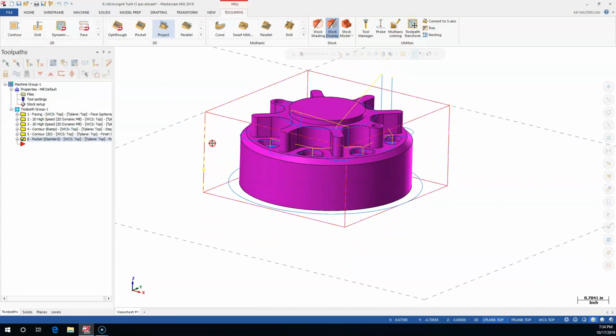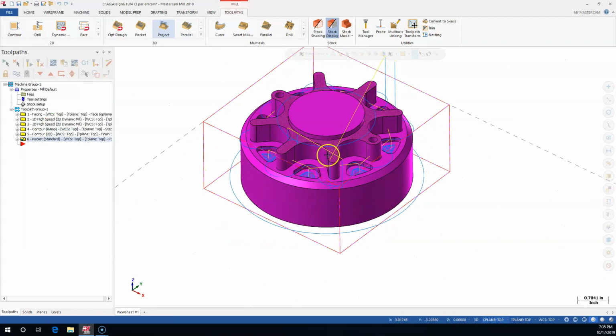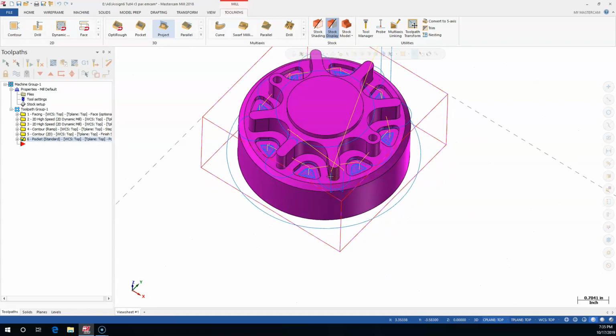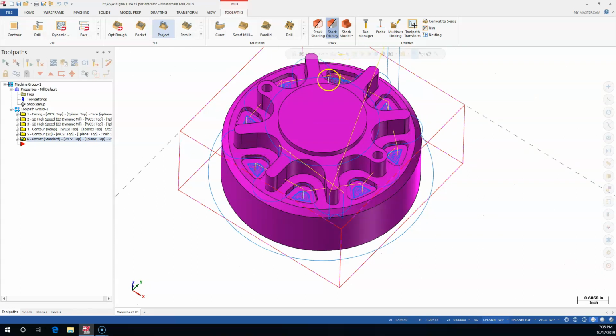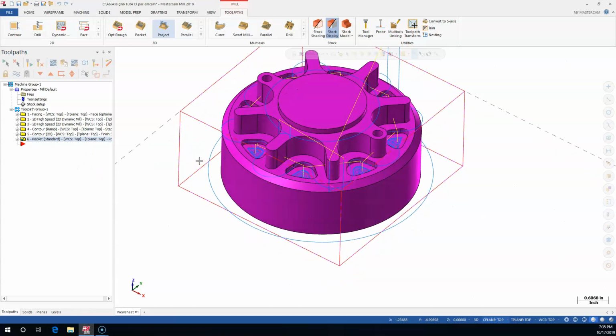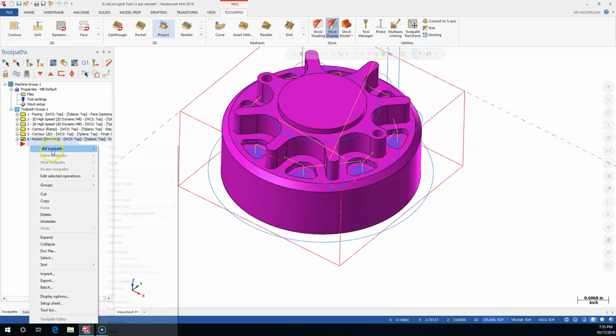And it looks okay on the depth since we're coming back from our zeros. So just have to be careful with those incrementals. I think better in the absolutes. I'll use the incrementals where they're appropriate. All right, so the 1/4 inch tool comes in. That sets our pockets, roughs and finishes the pockets.